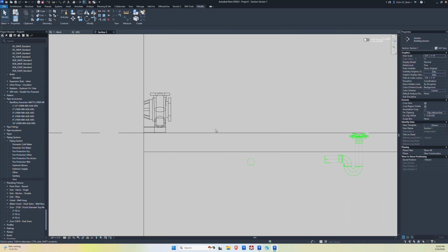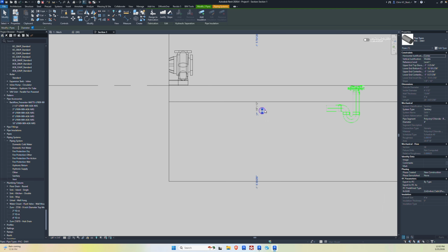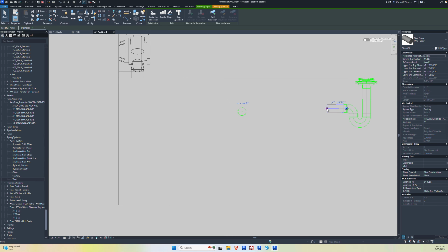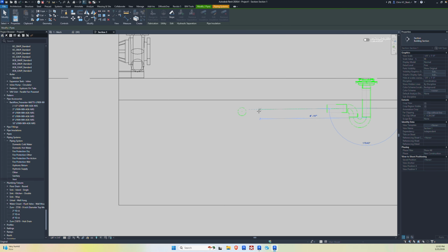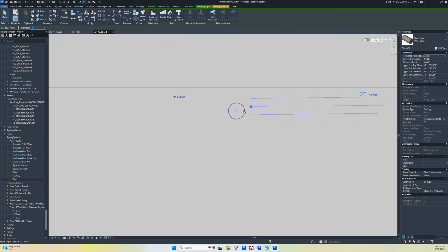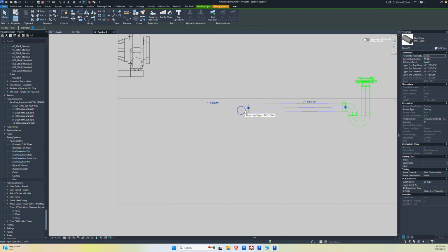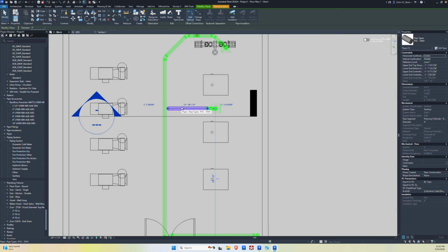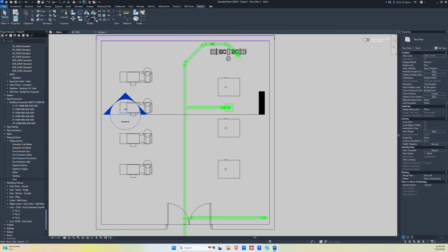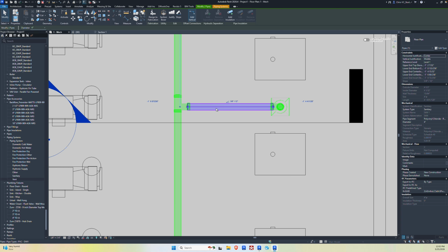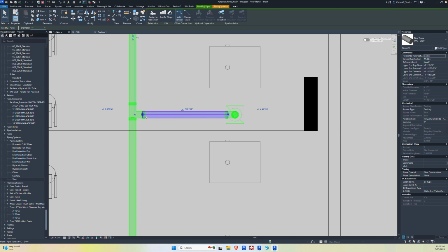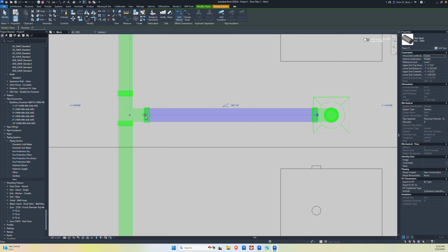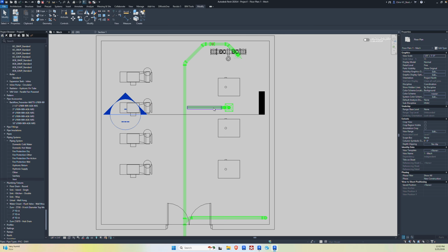And we go to the view, you can see that the pipe is here and this pipe is here. If we were to drag it down on slope, these two pipes won't work. If I try to connect them together using this, here it's not going to connect. Let's try it again just to make sure. And it looks like it connected, but now it made it 3/8 and it added another fitting here and there. And that's not exactly what we want.